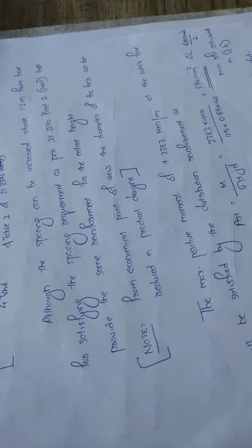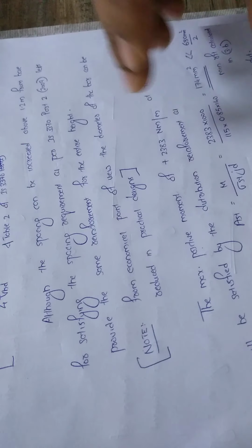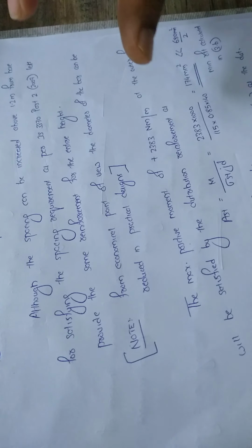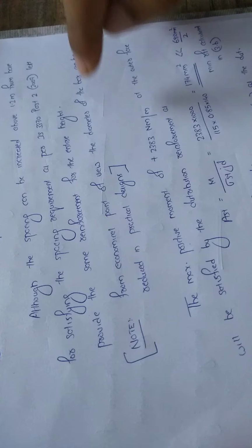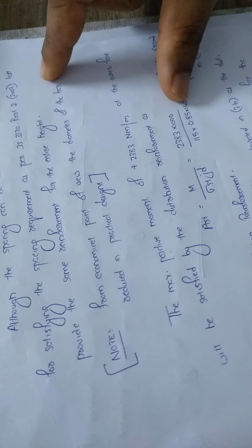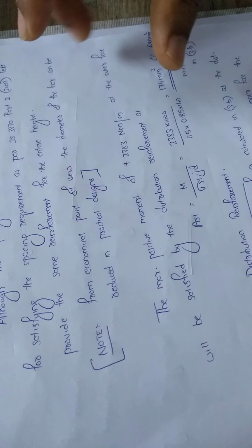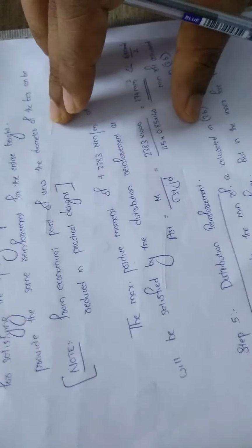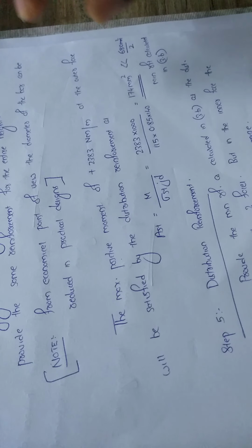You're going for a smaller diameter bar, and you can increase the spacing to the top portion and give the maximum reinforcement at the bottom portion to take the cantilever bending action. So this was again discussed in the introductory video on the behavior of the circular tank with fixed base. Okay, so in that video we discussed all the details.